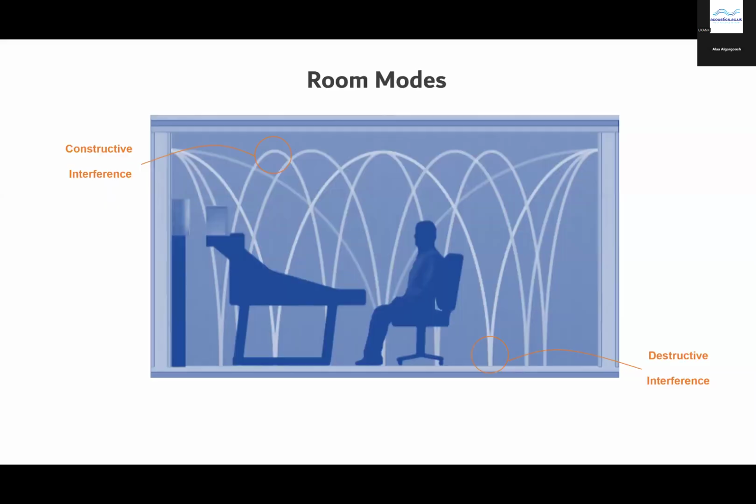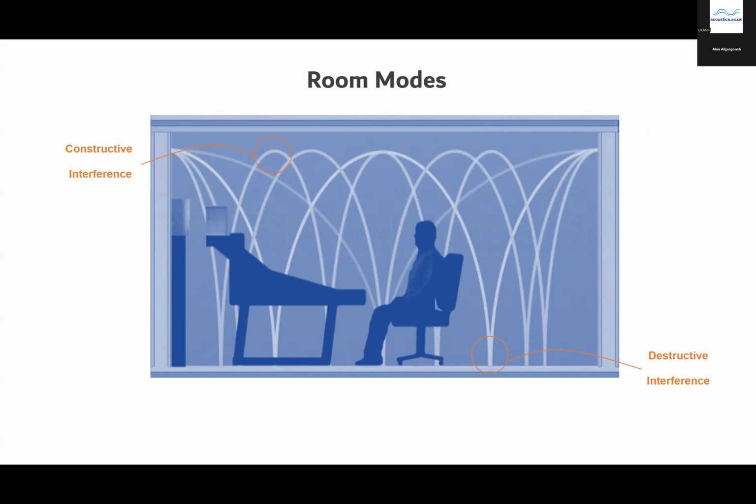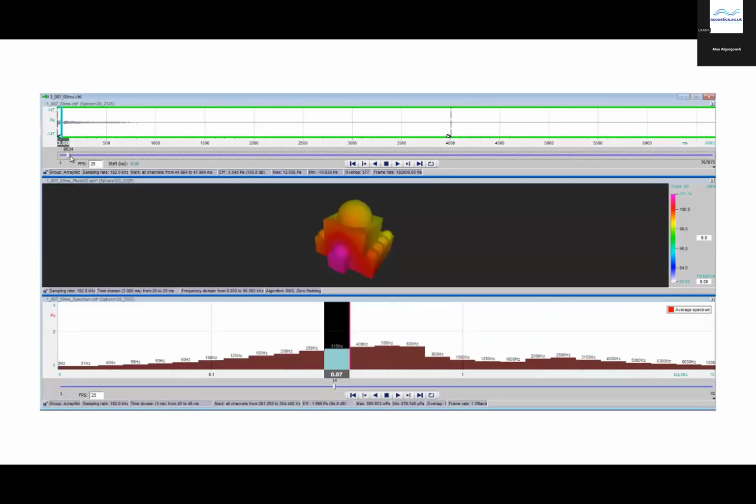The acoustic environment results from the room's response to a sound source, depending on the characteristics of the room in which the sound is propagating. This includes the room volume, geometry, and the materials present in this room. And room modes are the resonances that are generated through playing a sound in a room, and they are formed by constructive and destructive interferences caused by the sound reflections. They result in amplifying some frequencies and suppressing others. And this amplification is typically non-uniform, so it will be varied across different frequency bands.